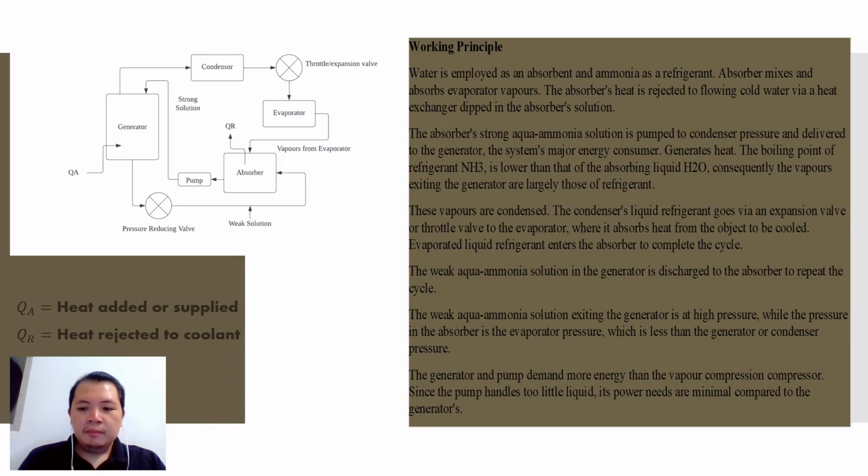Now for the working principle. Water is employed as absorbent and ammonia as refrigerant. The absorber mixes the evaporator's vapors. The absorber's heat is rejected to flowing cold water via a heat exchanger deep in the absorber solution.